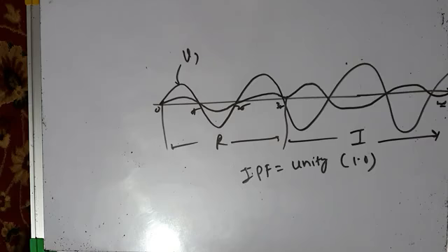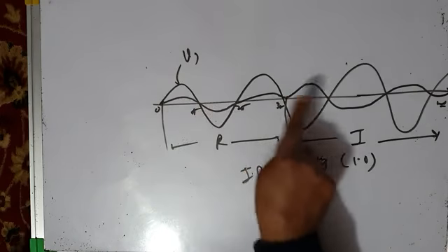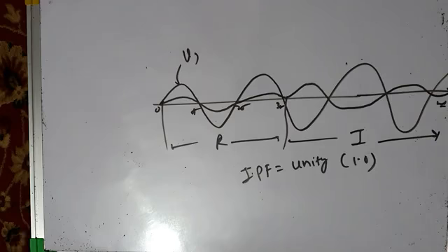In today's lecture we have discussed single phase unidirectional boost converter, two topologies, in continuous conduction mode, and then single phase bidirectional boost converter also in continuous conduction mode. In continuous conduction mode, the pulse width modulation or PWM technique that we use generally is hysteresis current control, HCC technique. The current is continuous, it is not discontinuous. You don't need any input filter. But for achieving this sinusoidal current, you need a closed loop system, and current loops are also required.